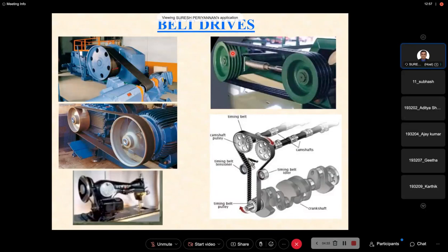Due to this wedging action, the wedging permits a smaller arc of contact while increasing the pulling effect of the belt. Then we can transmit more power because of the higher coefficient of friction created between the wedge surface of the pulley and the belt surface. The belt cross section surface is also in wedge shape.